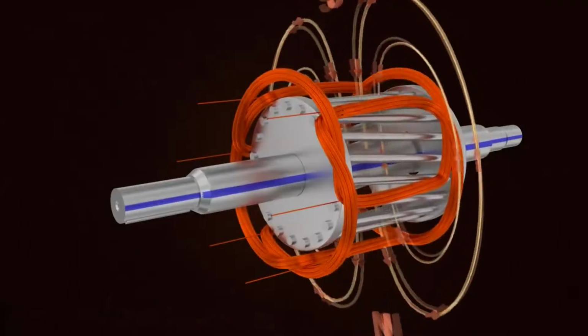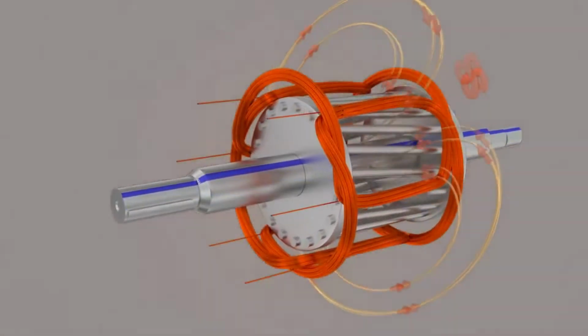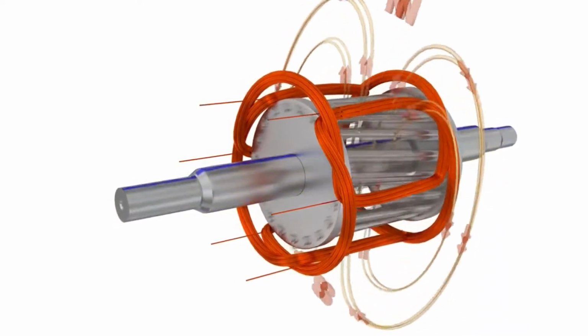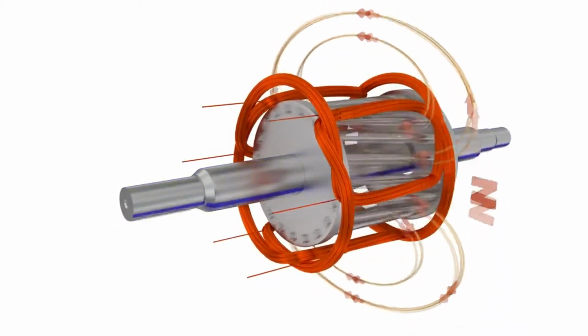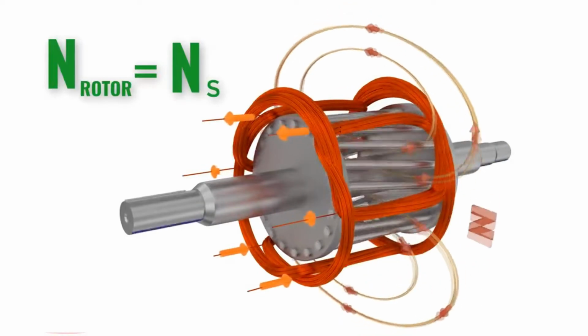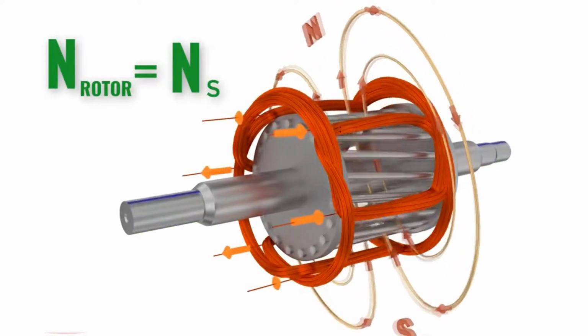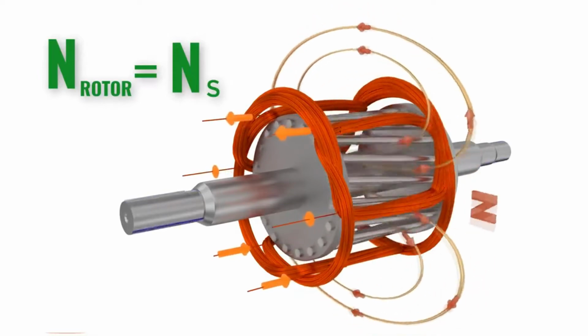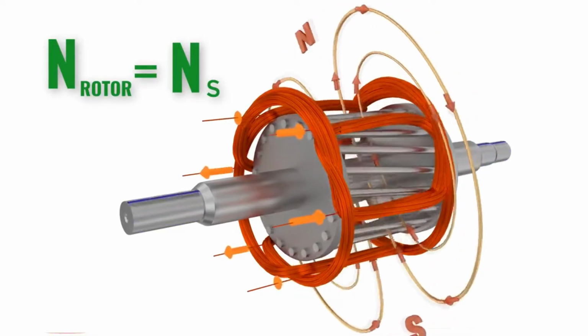An electric motor has two main parts, the stator and rotor. The rotor is a collection of conducting bars short-circuited by end rings. A three-phase AC power input is given to the stator. This three-phase alternating current in the coils produces a rotating magnetic field. The rotating magnetic field induces current on the rotor bars to make it turn.